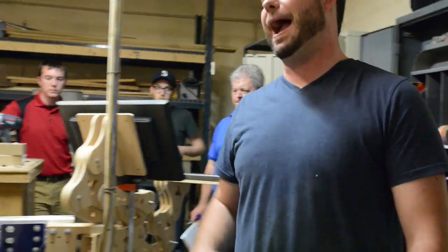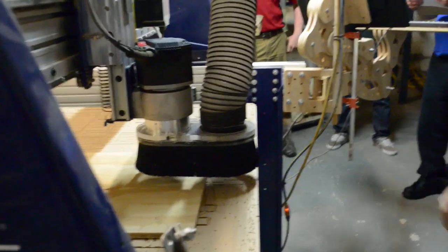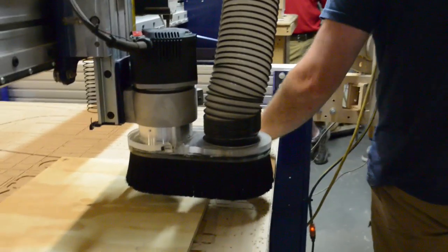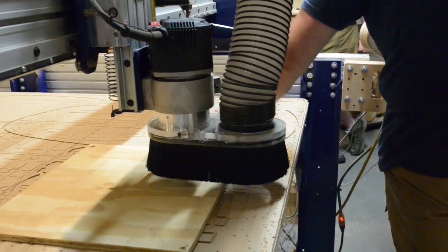That's it. It'll give you a little dialogue saying, great, you're zeroed. Remember to put the zero plate back. That's all you gotta do. Now your Z is perfectly zero to the top of this. If you eventually want to zero to the table, you just would do the opposite. Just put the zero plate down here and zero it to that.